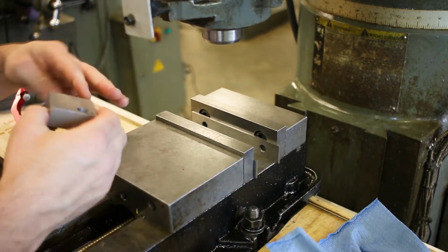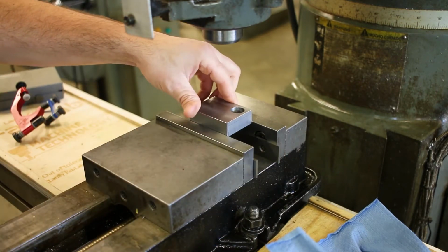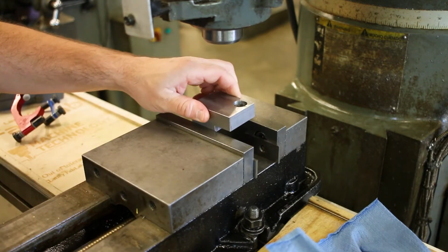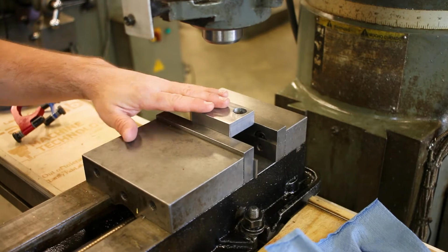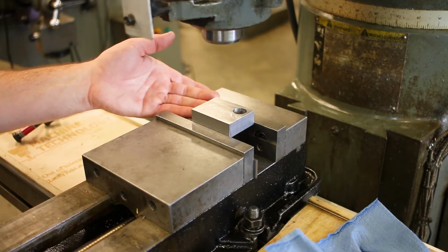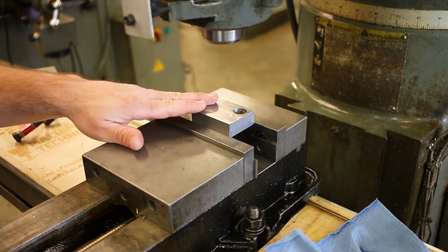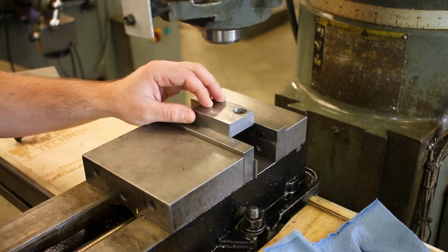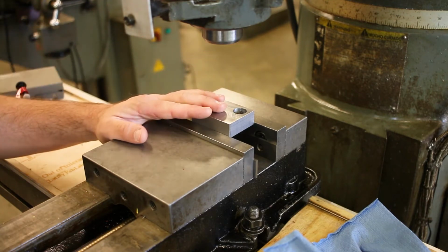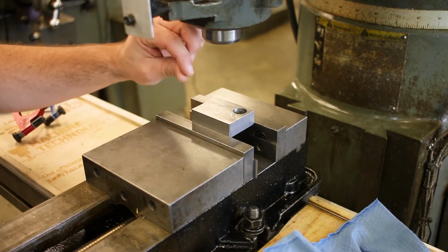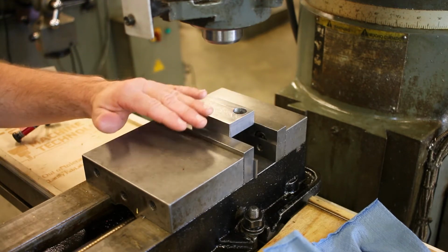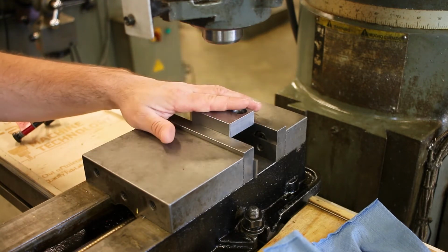Okay. Now, we're going to put the part in like this with those 2 little small surfaces down on the parallels like this. We're not worried about the orientation of the part too much because none of these surfaces are finished yet. We're about to start establishing our finished surfaces. So as long as the part's not cocked out too much, we don't really care that much about the orientation. As long as this orientation allows us to remove enough material to finish all of the surfaces, then we're okay.